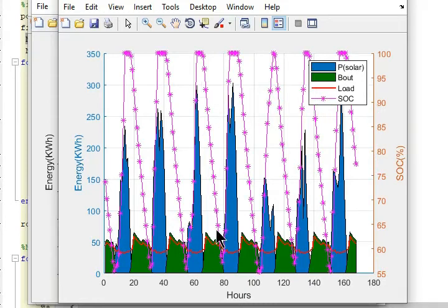So it means the battery is being charged when there is a solar peak. That shows that the battery is being charged in the daytime. When the solar is not available, this battery is providing energy to the load, so its SOC is going to decrease. The blue line is the battery discharging during off-day timing. At the same time, SOC decreases as the battery is discharging. So this graph at the same time gives the status of the battery, load, and generation demand.